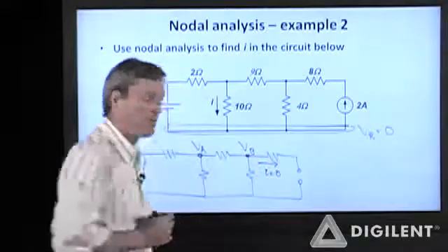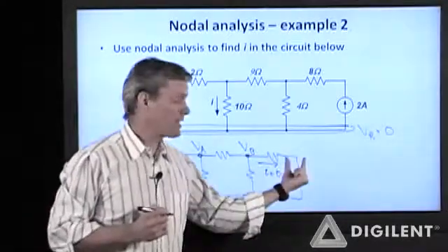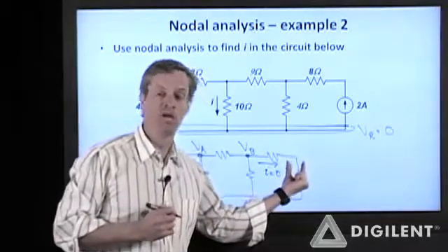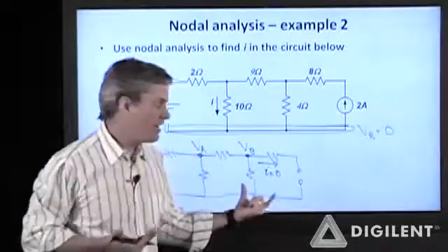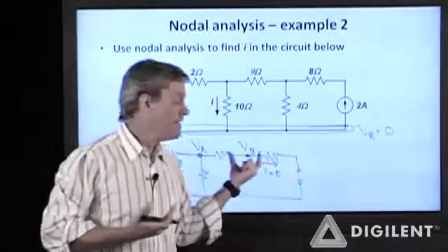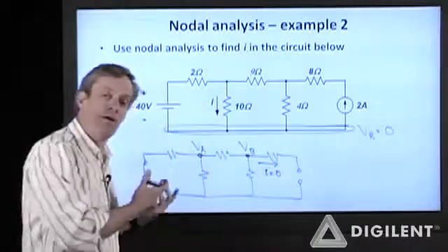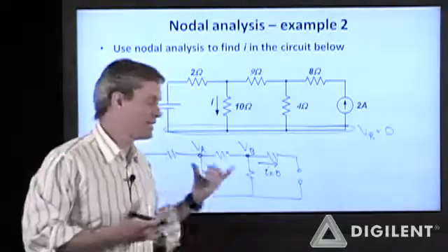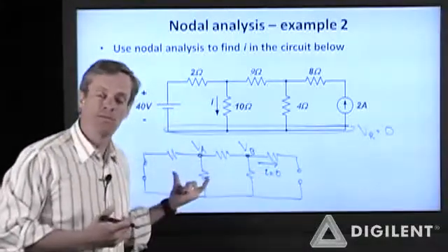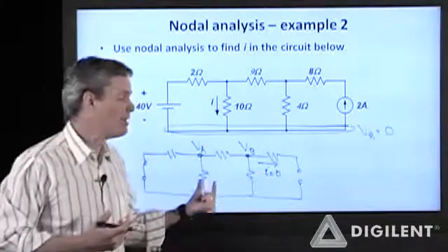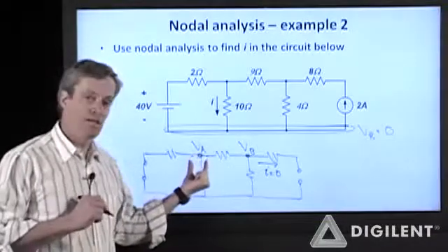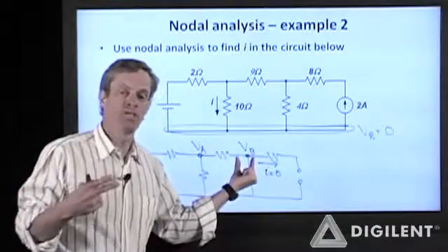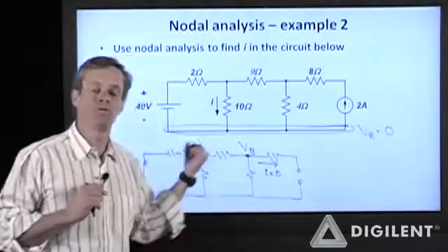Later on, we'll take a look and see, okay, if you misidentify this and say that this is an independent voltage, what happens? And if you keep your wits about you, nothing bad happens because you remember that nodal analysis comes from KVL, KCL, and Ohm's law. As long as you're consistent about applying those, some of the details about nodal analysis don't matter. But at the moment, we're going to claim that the only independent nodes are here at V sub A and V sub B. I have two unknown voltages. I need to write two equations, which I'll do on the next slide.